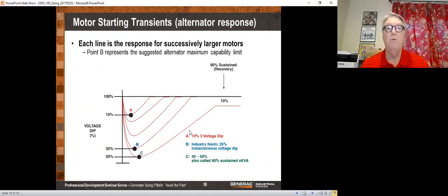And boom, the voltage goes down. Then the voltage regulator sees that the voltage has gone down and quickly causes that generator to recover. It does this in much less than a second. So it happens very quickly, but if it drops too low, you could have contactors falling out, PLCs falling out, elevator starters falling out. So that sudden drop is very important.